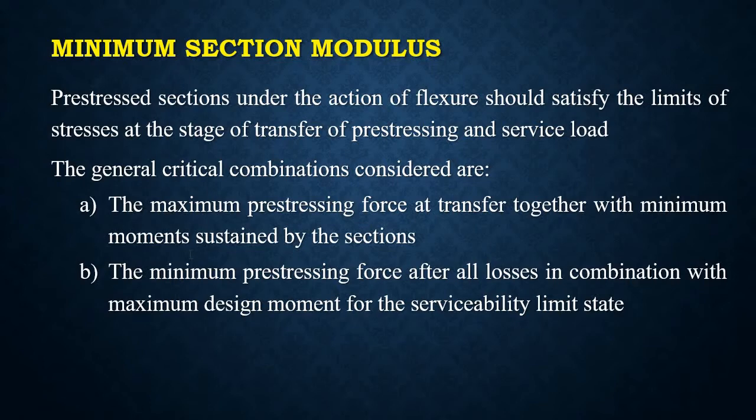The next combination is the minimum prestressing force after all losses in combination with maximum design moment for the serviceability limit state. These are the two combinations: maximum prestressing force plus minimum moment, and minimum prestressing force plus maximum design moment.